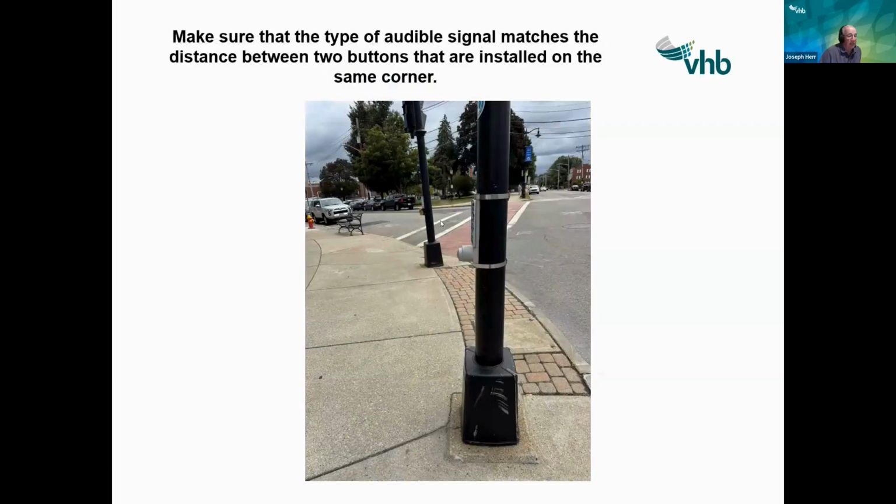Next, make sure that if the buttons are close together, they have the appropriate sound. Typically, if they're less than 10 feet apart, they call for text messages to say, hey, the walk signal is on across Main Street, or the walk signal is on across Side Street.